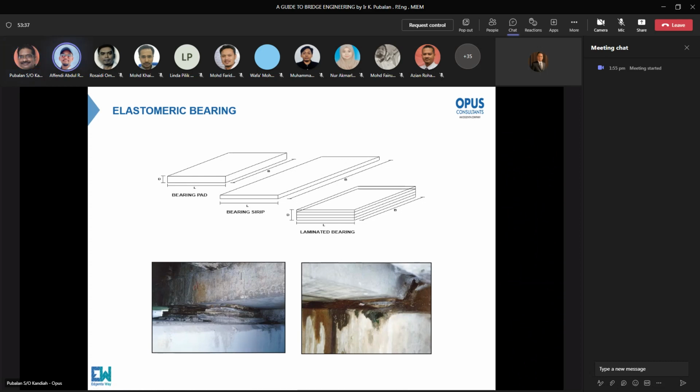There must be a pair, because on the other side will be a mechanical pot bearing, isn't it? Not exactly. Depends. For a mechanical pot bearing, we will see in the sketch later. I also have a slide on that. Mechanical pot bearing is for when your bridge has some curvature and there's some slight rotation to it. This laminated bearing cannot take rotation, very little.